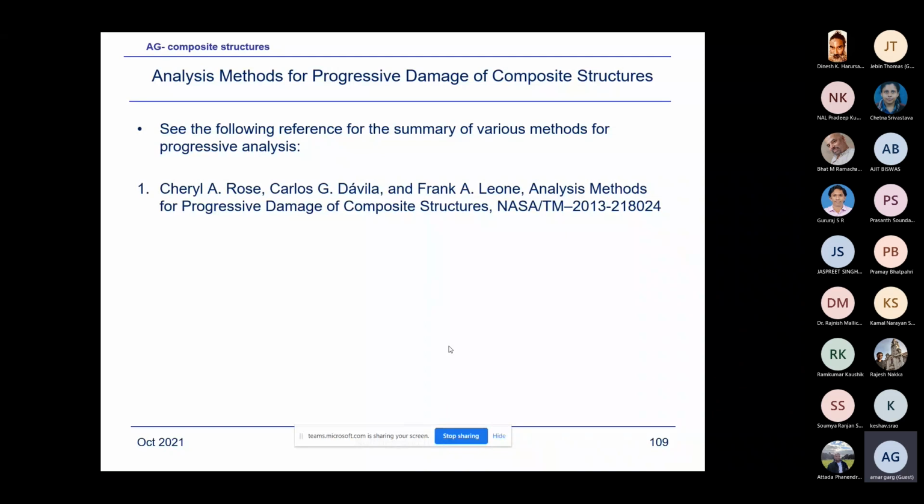So it puts a lot of pressure on the resources if you have to make models of each of the regions which you want to analyze. So usually what will be done by the industry? They would build some panels, test them, make the models, analyze using the FEM models, and compare with the test data. That is a model verification essentially.